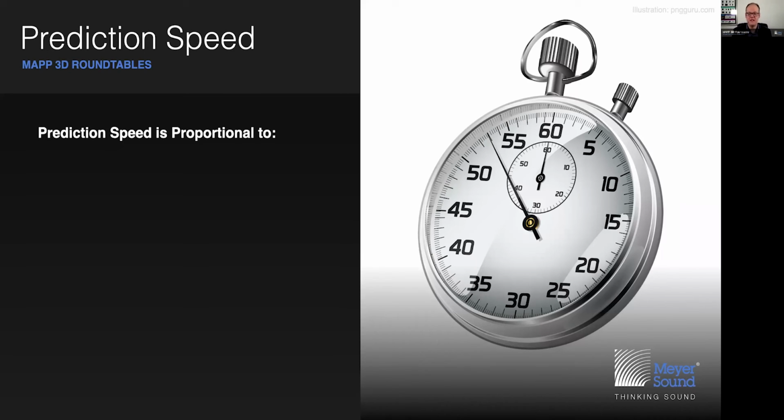The prediction speed, or the time that you have to wait, is proportional to the mesh density. And that means that every surface, every plane that you activated for prediction is chopped up into little triangles. And the vertices where the triangles meet at the nodes, that is where SPL is calculated. And that means that the higher the meshing density of a particular face, a particular surface is, it should not come as a surprise that the prediction speed goes up proportionally.